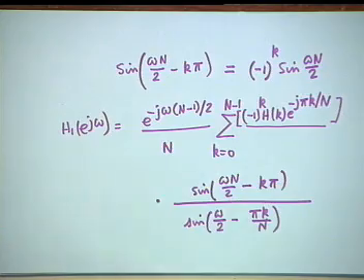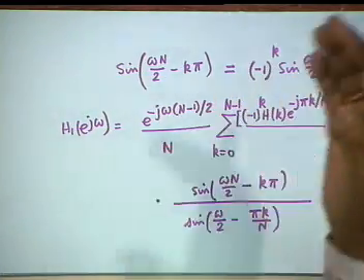That is the elegant form, and this is the form that should be utilized for computation of the frequency response function, unless capital N is very small, maybe it consists of 1, 2 or 3 terms, then you do not bother. When will it consist of 3 terms only?